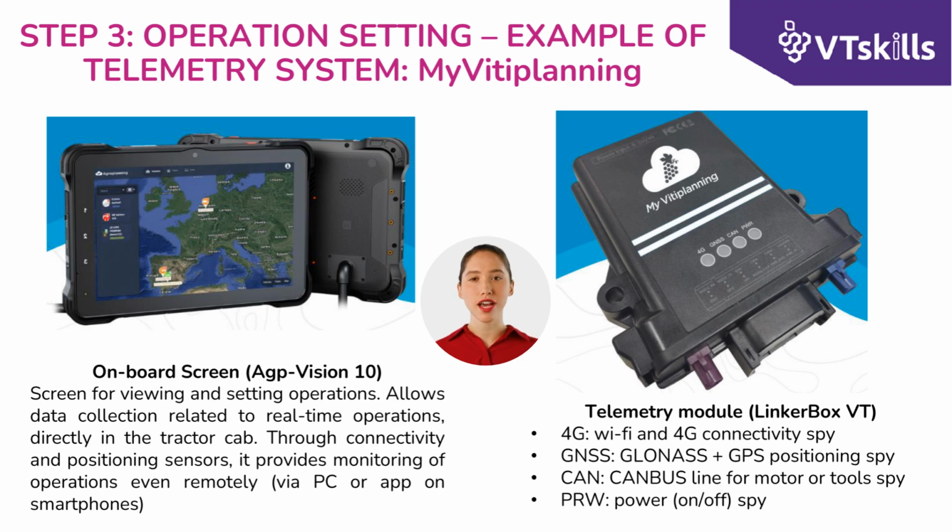The body of the technology is a board for acquiring and sending digital and analog signals connected to the tractor and operating machine sensors. Different communication protocols are available, ranging from Wi-Fi to Bluetooth, to ensure maximum versatility. Recently, 4.0 connection systems have been developed to monitor the data communication lines inside tractors and operating machines, such as the CAN bus protocol.